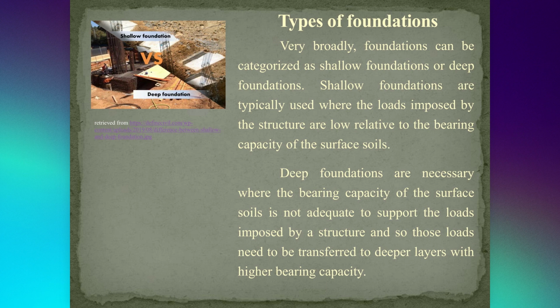Types of foundations. Very broadly, foundations can be categorized as shallow foundations or deep foundations. Shallow foundations are typically used where the loads imposed by the structure are low relative to the bearing capacity of the surface soil. Deep foundations are necessary where the bearing capacity of the surface soils is not adequate to support the loads imposed by a structure, and so those loads need to be transferred to deeper layers with higher bearing capacity.